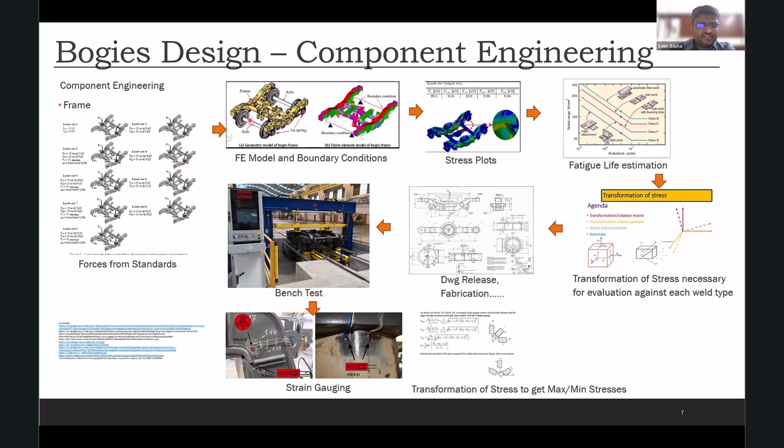And we model the frame in a CAD model as we want, given the constraints that we have. And then we have software like finite element analysis software, wherein we apply those forces and see what stresses come up. Are the stresses within the limits or not? And if they are not within the limits, then we keep on iterating the design to ensure that the stresses are lower than the limit.